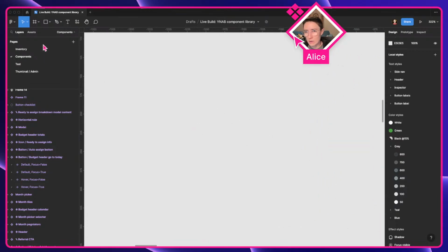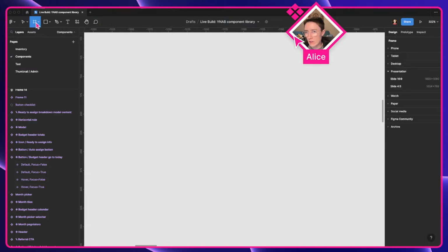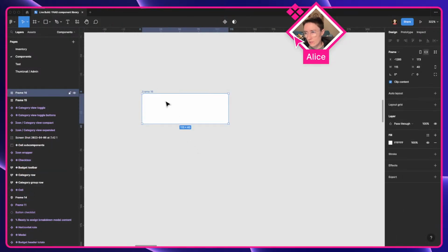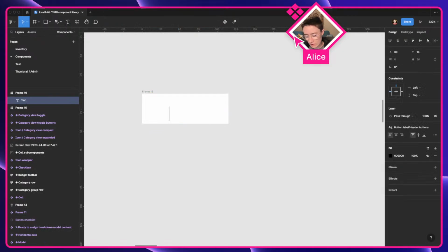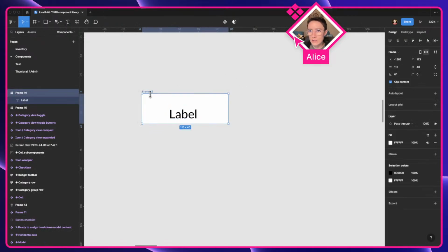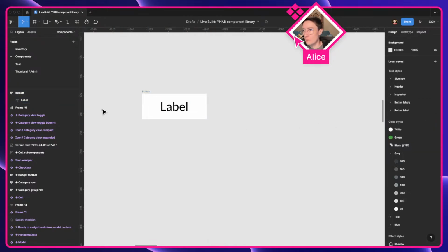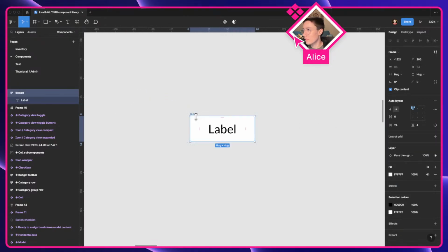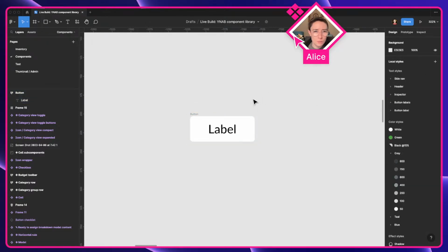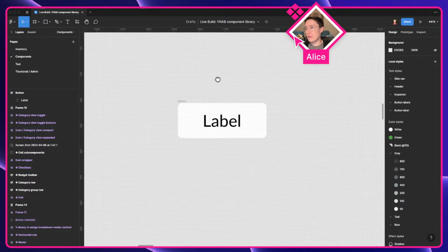So I'm going to come over to an empty corner of the canvas here. As ever, buttons are a great example. Let's throw some auto layout on this and get some reasonable numbers here. We'll do 24 for top and bottom, 0 space between. Okay, not the cutest label you've ever seen. 4 pixels rounded corners, but we've got something to work with here, right?